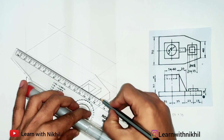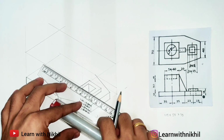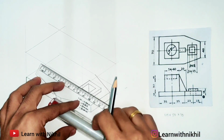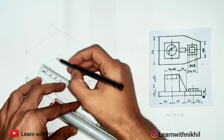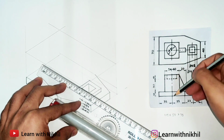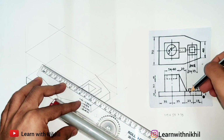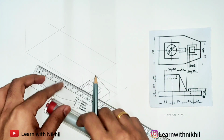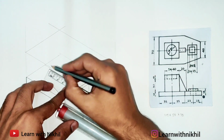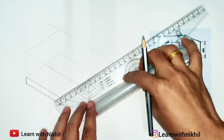The square dimension given is 40. This is the center line and the dimension given. So from the end 35. So from here 35 will be the center point. From behind 35 millimeter, I mark the point. Now keeping that as the center, we have to create a square of 40. So keeping that at the center, 20 millimeter on both the sides. So from here 20 millimeter here and 20 millimeter below. So the total distance is 40.